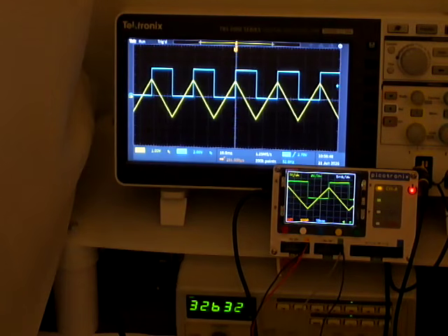Okay, so there we're down at about 32 Hertz. So that's the sort of time base that you would use if you were looking at things like 50 Hertz noise, low audio, various signals that are down in the sub 100 Hertz bandwidth.